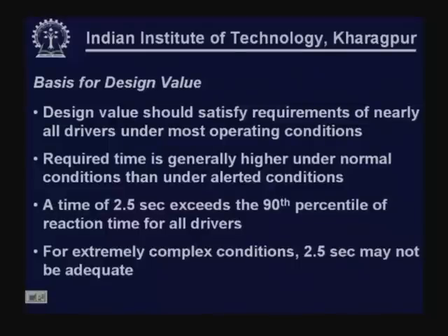It is also found that a reaction time of 2.5 seconds exceeds the 90th percentile of reaction time of all drivers. One can justify that, that means if a 2.5 second value is taken, then that exceeds the 90th percentile of reaction time for all drivers. So, a 2.5 second reaction time is generally accepted for design purposes.